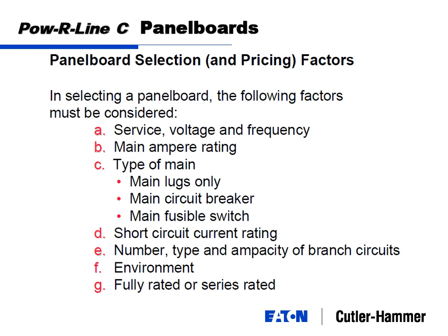We have to put that sticker on in the plant by NEC code. They can't just mail you a sticker and you slap it on. Well, in theory you could, but if the UL inspector found out about that, he would not be happy. So we need to actually do that in the plant. And the one thing we do, other than the sticker, is to actually put a removable neutral to ground link.